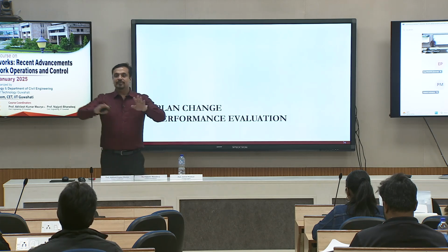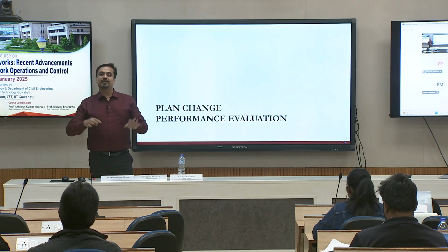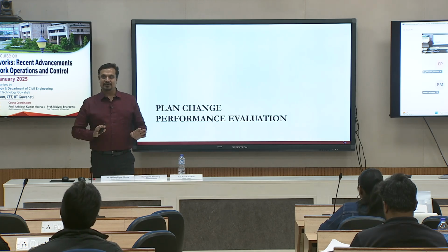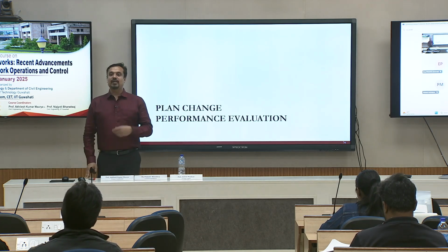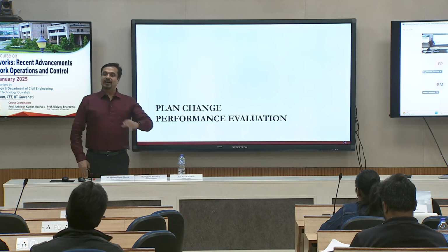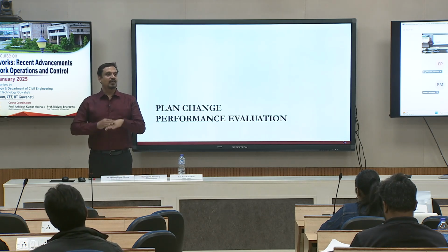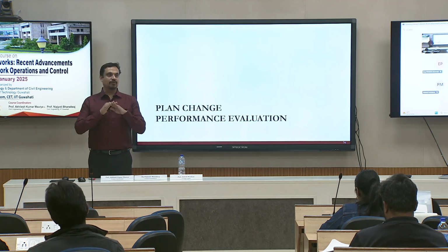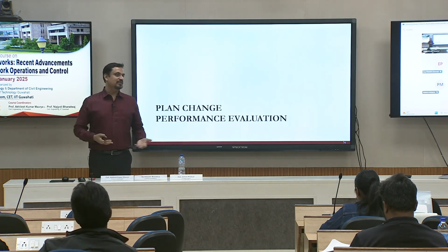Yeah, so that has been considered by the way you have defined your phases. Okay, but that indicator is also important. It's just whether we have a data set for it or not. But that we have done when defining the phases: I do not let a permitted right turn for an approach where I know there are 3 lanes or 2 lanes coming. I have done that.